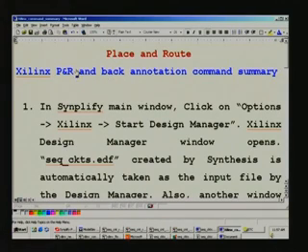The next step after place and route will be what is called back annotation. Only here the actual gate delays etc. will come into the picture. Subsequent to this you have to take the back annotated file, which is also a .v file, and take it into the ModelSim simulator and run the simulation once again, and satisfy yourselves regarding the functionality, and therein you will get actual gate delays reflected.